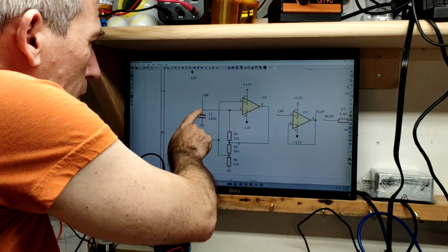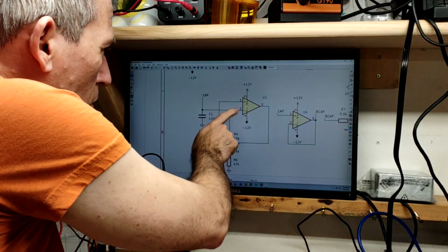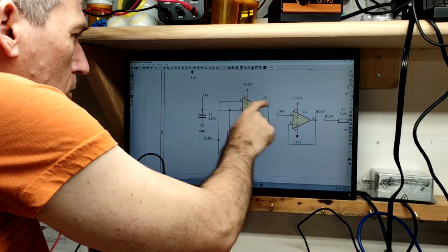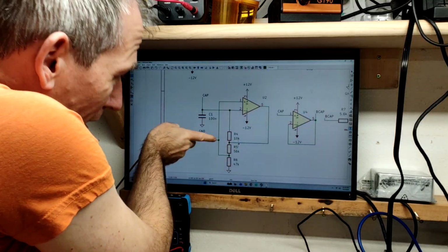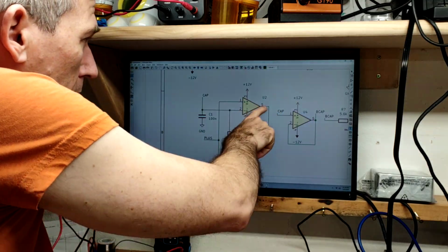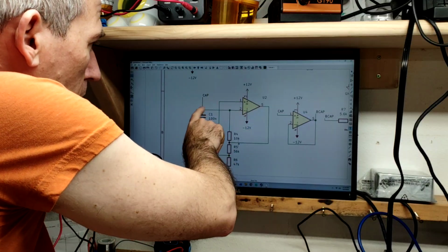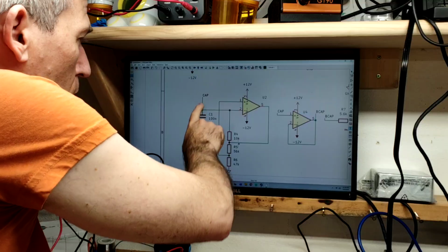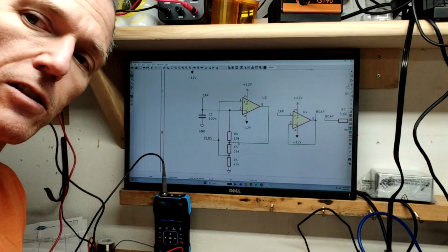but this capacitor has 0 on it, so this current's not going to be able to go in there. It's pushing negative volts here. It can't go. Conventionally, we can think of the current as going this way. It's pulling it through this resistor because it has a negative voltage here, and this started at 0. So what'll happen is it'll pull current up from the ground through the capacitor, and the capacitor will charge.